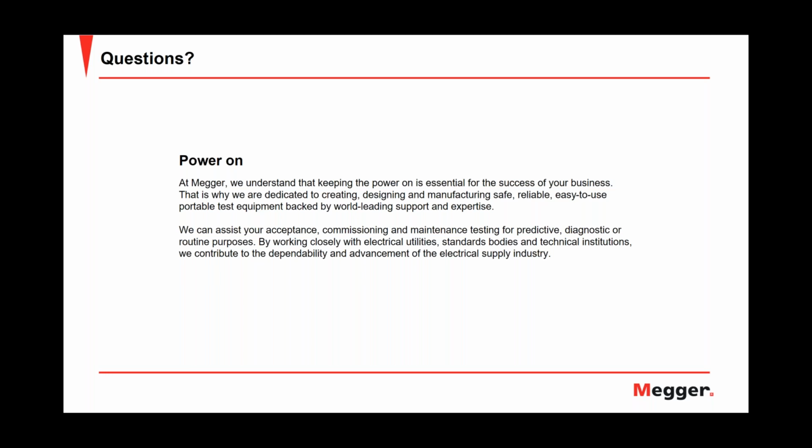All right. So Henning, what do TDR and ARM stand for? Oh, TDR stands for time domain reflectometer, because like Javier was explaining, many people believe it's a distance meter. It's really an impedance meter. It measures impedance in the time domain, and that's where the name comes from. So we're looking at changes in impedance along the cable, and that's where TDR comes from.